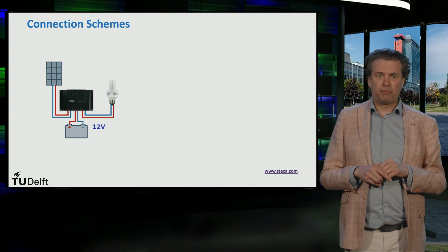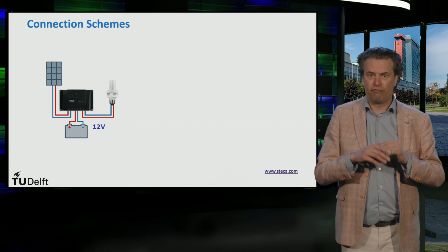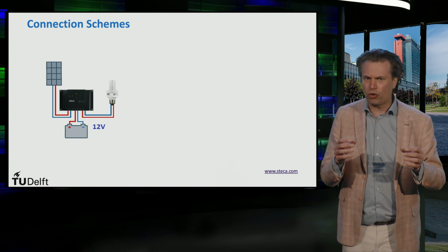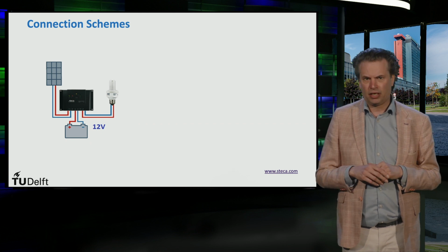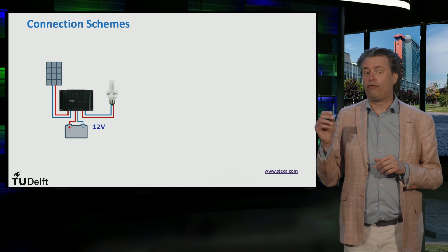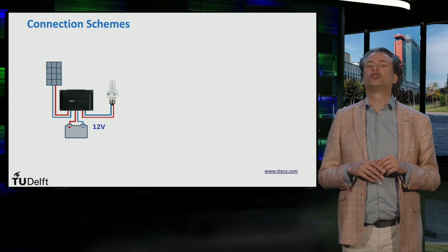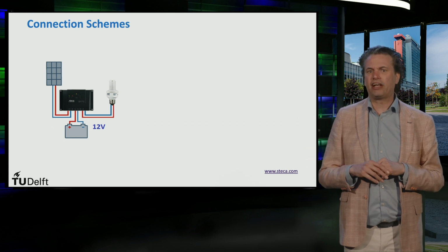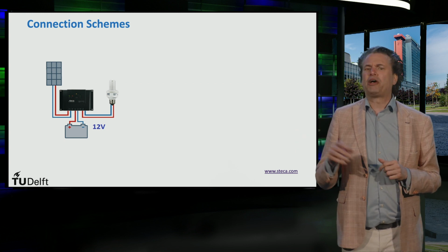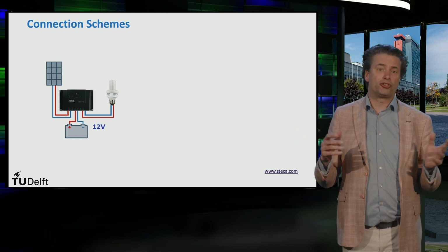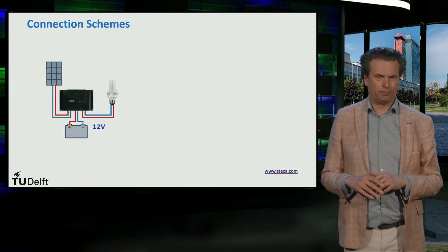Such a PV system is more common in very remote areas where the loads comprise just a few DC lamps and fans. The advantage from this is that a 12-volt system is enough to power those loads. Hence, it's relatively safe to operate because of such low voltages. Also, by using such a simple PV system, the cost involved is also less.